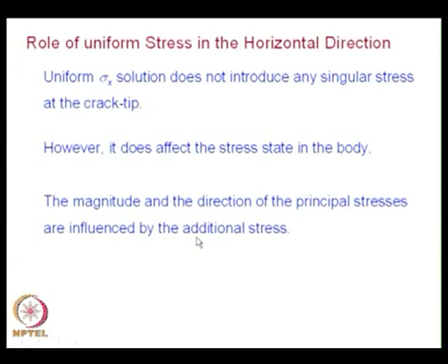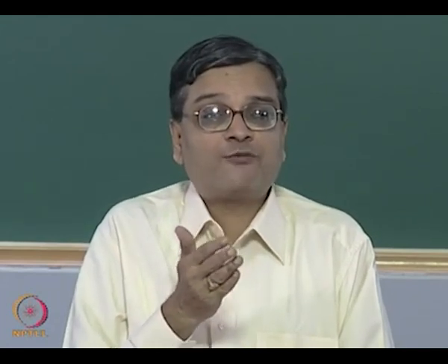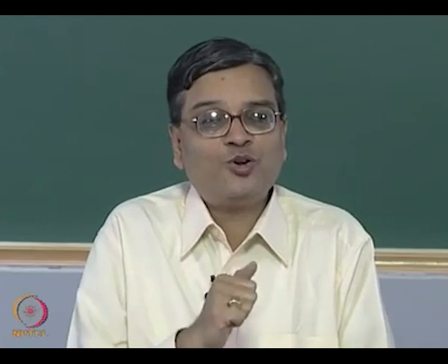You cannot ignore it. See, we are going to discuss towards the end of this course theories related to which way the crack would propagate. If you look at only the singular solution, you will have in the case of mode 1 what is known as self similar crack propagation. If the crack was horizontal, it will propagate in the horizontal direction, but people have found turning of the crack also occurs in the case of mode 1. How do you go and explain it? Unless you bring in higher order theories, such things cannot be explained.